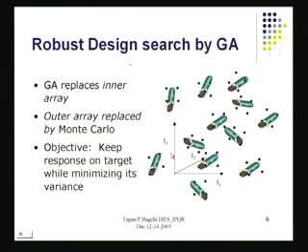Now, this model is also there. This is also a search. We're creating various different designs and subjecting those to environmental impact. Now, what do we do? How can we utilize that in our engineering design? We'll create these prototypes as per GA guidelines, genetic algorithmic guidelines, and then subject each of these prototypes to what we call Monte Carlo simulation of the noise. So I'm producing these prototypes by GA, and these prototypes would be a combination of some design variable settings. Then I shake them up using Monte Carlo.